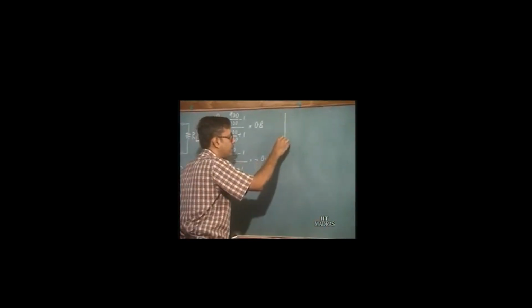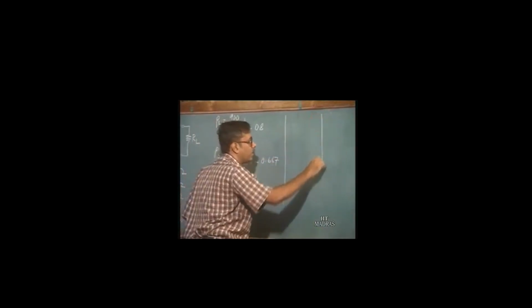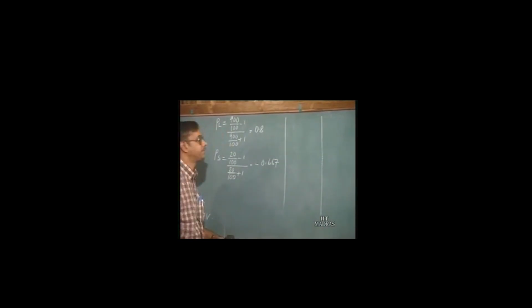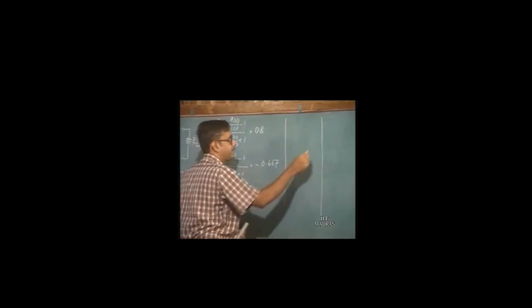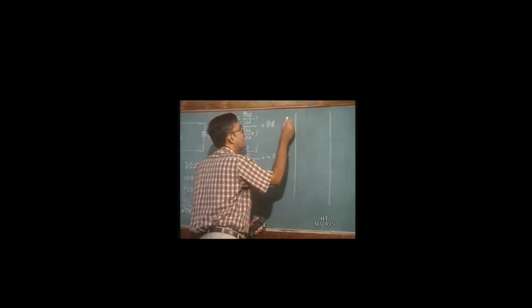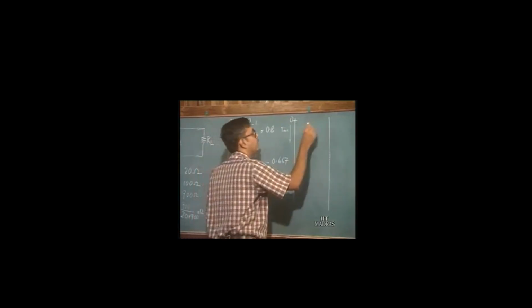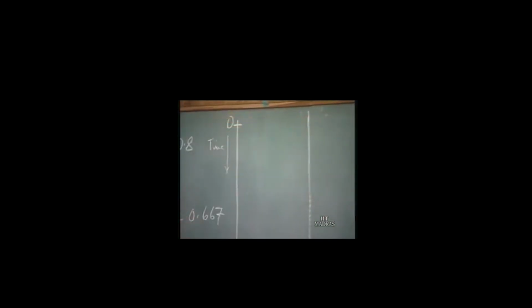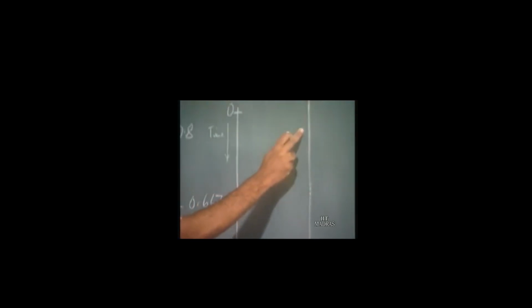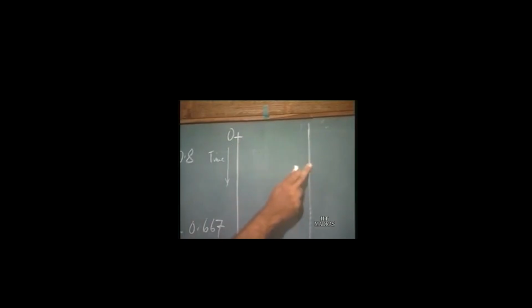So these are the reflection coefficients. Now, to find out the waveform, there is a particular diagram which is drawn like this. Suppose this axis on this side is the time, and at this end it is 0. This is the source end and this is the load. It takes a time Td for the waveform to move from the source end to the load end.